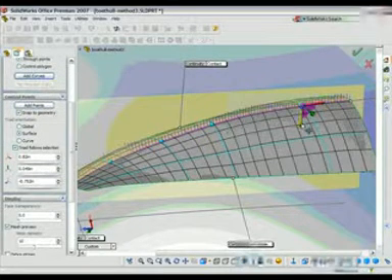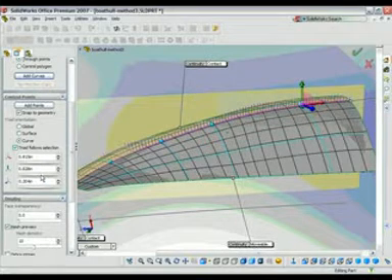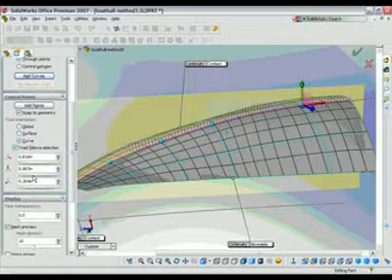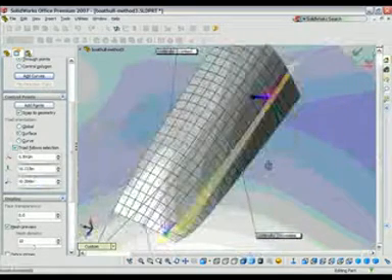I can also use our property manager over here that has thumb wheels to control these vectors for the triad. This gives you much more precise control. I can use my Alt key to half the value as I twirl the knob, and then the Control key to double that value.